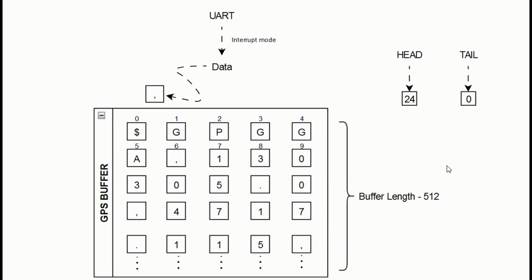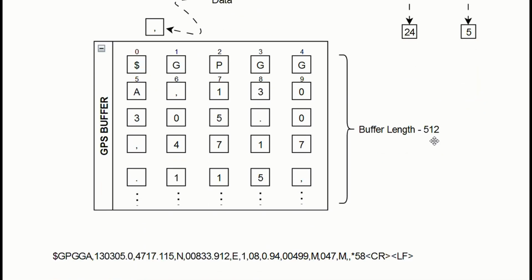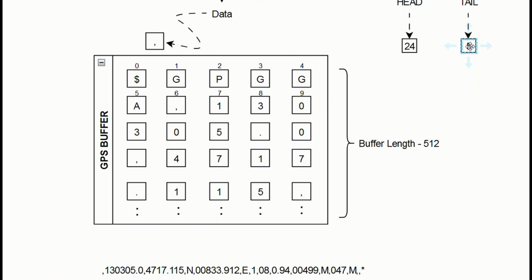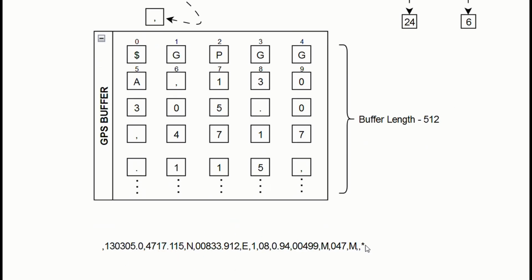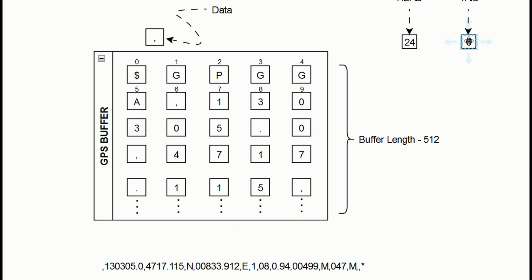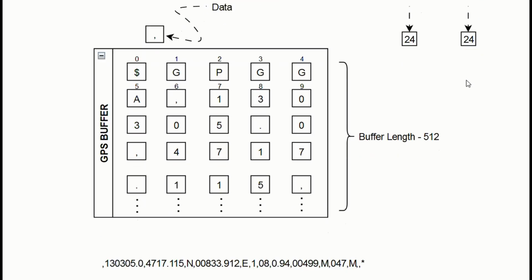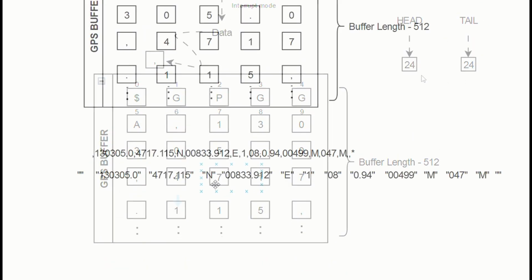Simultaneously, a function peeks into this GPS buffer and searches for the interested dataset, GGA or GSV in our case, character by character. This causes the tail index to increase as well. If the dataset characters match all along, we copy the sentence related data from the comma next to the dataset identifier until the asterisk symbol, explained in the data format section earlier, to a completely new buffer. Then, through some careful function manipulation, the useful info is extracted. Mind you, all of this is happening at a very high rate.